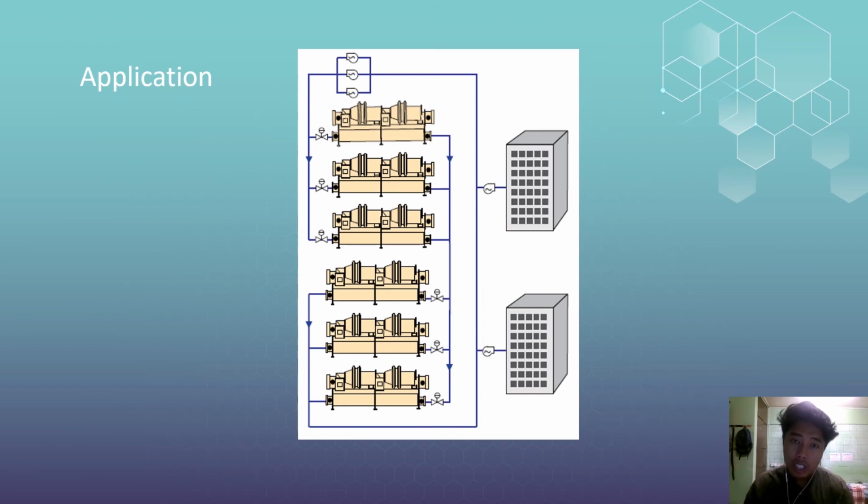In rare instances, saltwater or brackish water can be applied if the system uses an intermediate heat exchanger, or if the chiller is constructed with special tubes. Furthermore, large chilled water systems can be challenged by site power availability. Transformer size may be dictated by local regulation. On-site power generation may be part of the project, leading to using higher voltage inside the chilled water system to avoid transformer losses and costs.